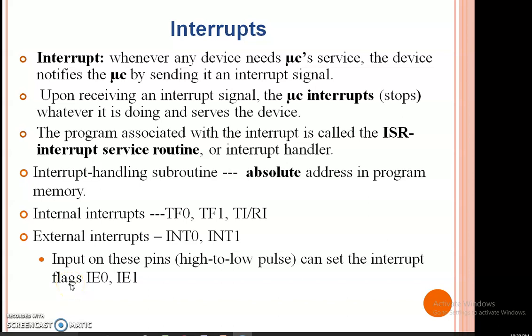Students, today we will learn about interrupts. What is the general meaning of interrupts? Disturbance. So here the 8051 can receive interrupts from the external devices which are connected to the INT0 and INT1 pins, or it can receive interrupts from the internal architecture also.